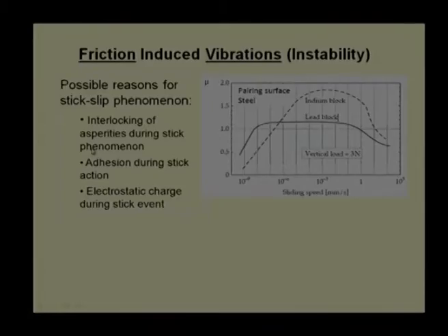A similar phenomenon will occur when there is an adhesive component, or the two components are getting welded at asperities. When you push it and leave it, what will happen? The junction will be broken or sheared, and after some time they will be formed again.